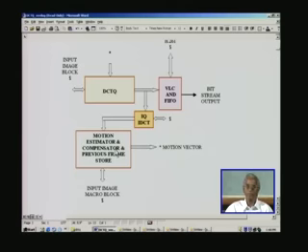So we take a macro block, as mentioned earlier, in the current frame and look for the shift in the previous frame, and that is what this algorithm does. Finally it will create what is known as a motion vector, which will say it has moved by such and such place. The xy coordinate will be transmitted, using which the receiving end will easily reconstruct that motion, and there will be no need for sending the previous frame, only that particular small macro block where there is a motion change.